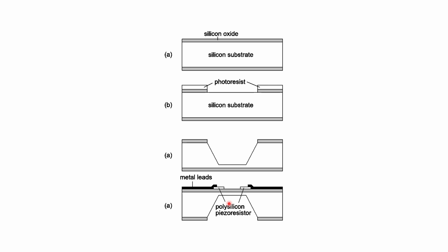What we mean by a robust process? A robust process is one that is not sensitive to over etch or timing error. If you have a process where the result is very much determined by the timing, then you don't have a robust process. In this case, if the etch rate is fixed and you etch a little bit further, then the membrane thickness would change. And that would be not ideal for a pressure sensor device. So only use this as an example.